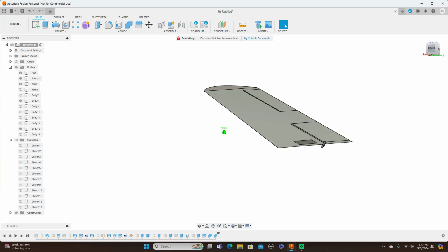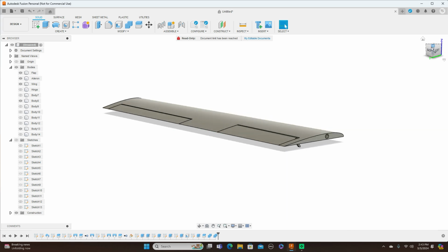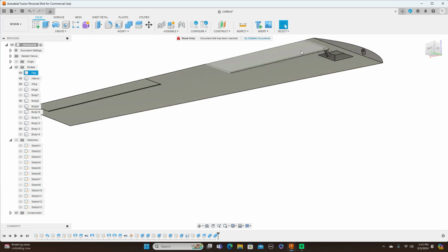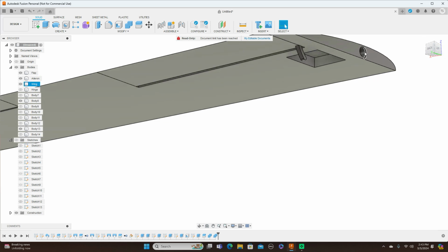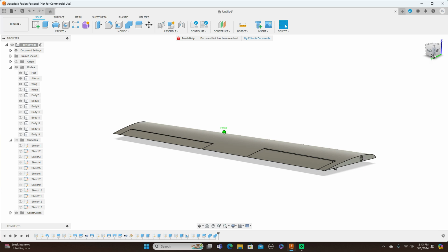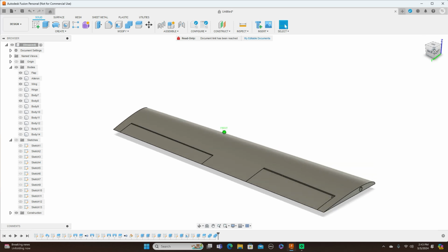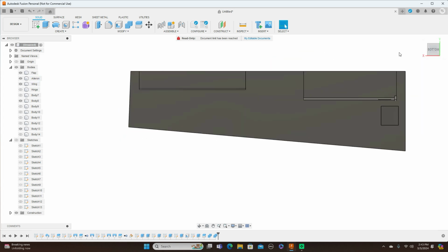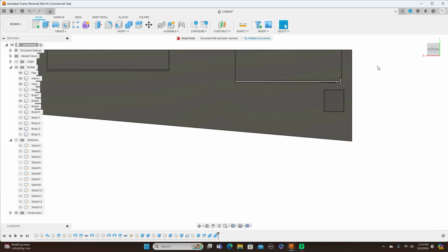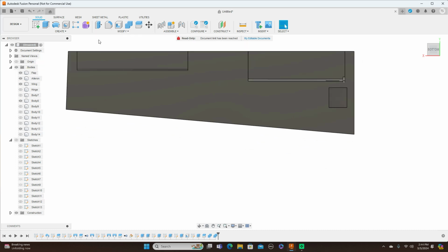And so now I showed you guys how to make the wing, cut out ailerons and flaps, how to put horns onto the flap and the aileron, how to cut in the wing tube, a slot for the servo, how to do the wing structure here, and let's say if you wanted retracts in this, that wouldn't be difficult to do either.